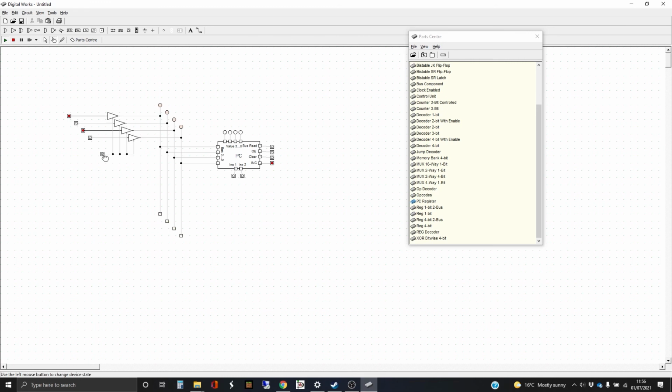Okay, so let's put a value in. Let's use 1010, one of my favorite binary numbers, which is 10. And so we need to do a bus read, and that should give us the 10. We'll disconnect that, and then we've still got the inc. So let's do our 2 phases and check that it's counting from there, which there's no reason why it shouldn't be. And then finally, let's just take off the inc and check that it's not incrementing. Yes, that's fine. It should be going round the 2 registers. It's just nothing's being added. So it looks like it's working.